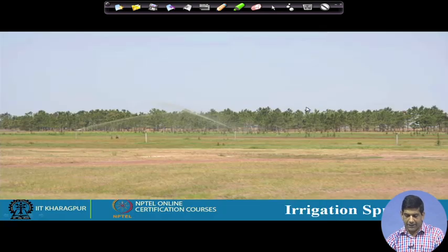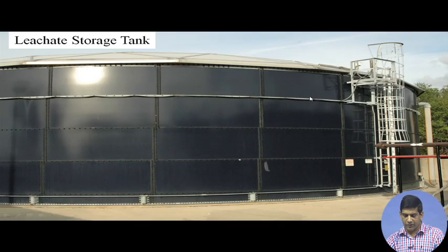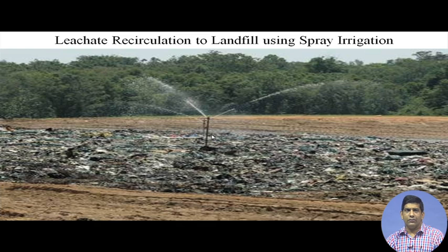Okay, and then it is sprayed. As you can see, it is sprayed around the landfill property. So that's the irrigation spraying done along the landfill property for this leachate. Leachate storage tanks. This is how typical storage tanks look like. Many times it has a double layer. So you see an outer layer, and then we have an inner layer just to prevent any leakage. So even if the inner layer gets broken for some reason, this outer layer will prevent the leachate from going out. So those are used as well.